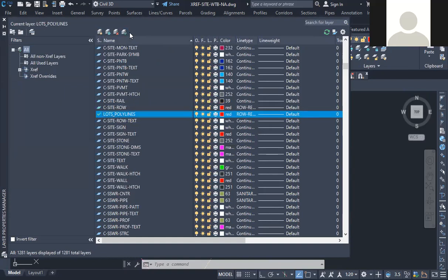But if you have a bunch of lines that overlap one another and you go to print that, you're never going to see the line type. But you still want to have that line. Okay. See this column? It's a plot layer. If you select that and turn it off, it is visible to you on the screen, but it won't print out on the PDF or the paper copy when you go to print.